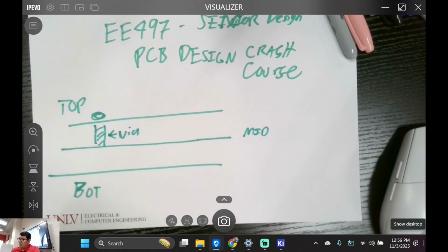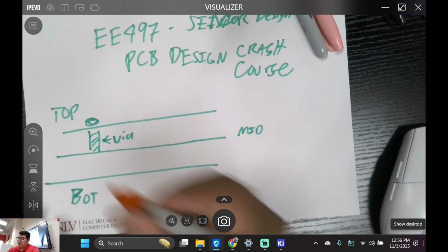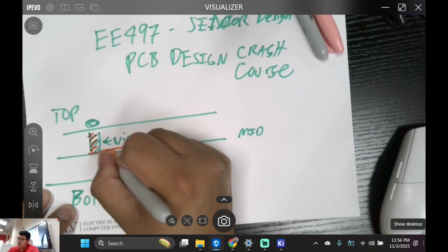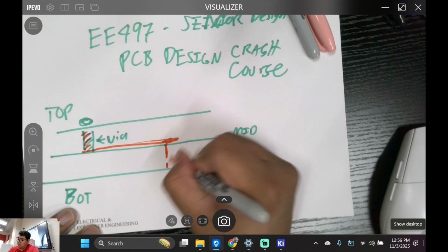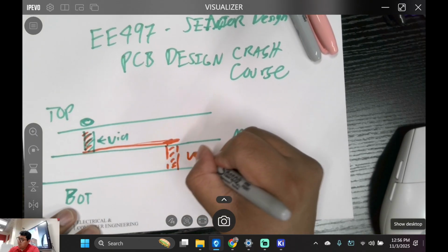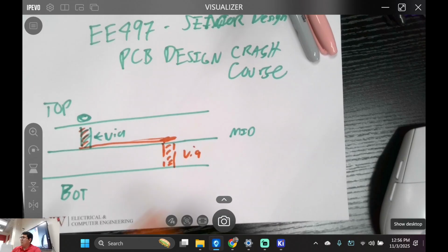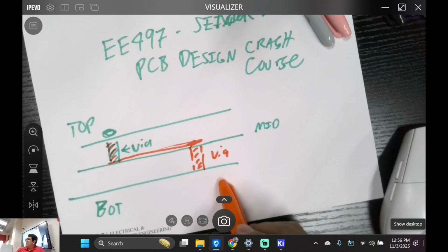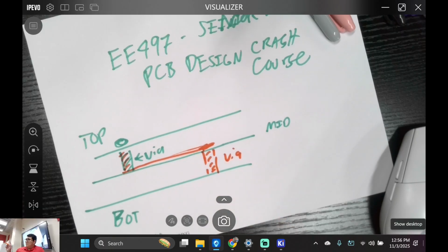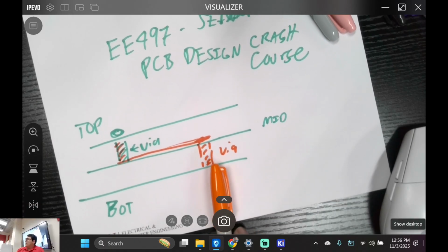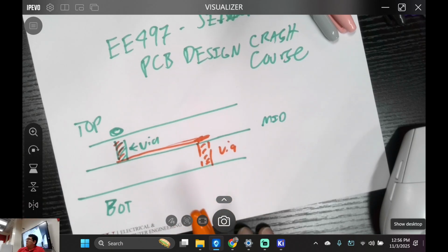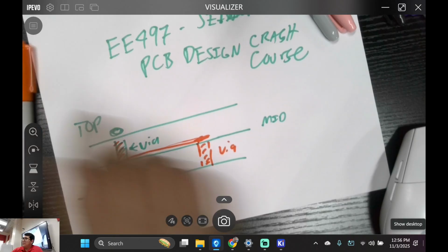And then you're trying to draw your wire. Let me just draw it in a different color. You're just going to draw your wire, and then I'll do another tunnel. Basically, vias are these internal things that you're going to be using in PCBs. Most of you, I don't think, are going to be doing microvias, but this is something you are able to do if you have anything more than 2 layers, like 4 layer boards. Is that good with everybody?